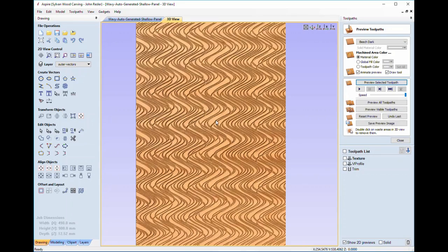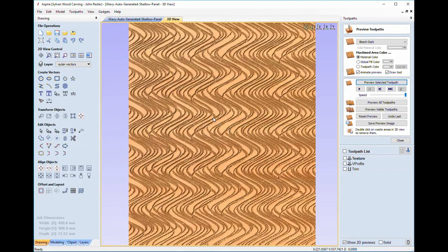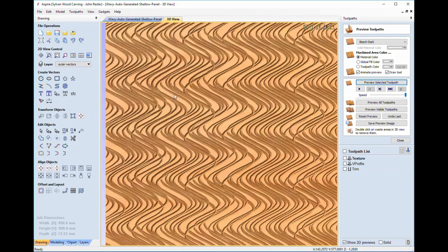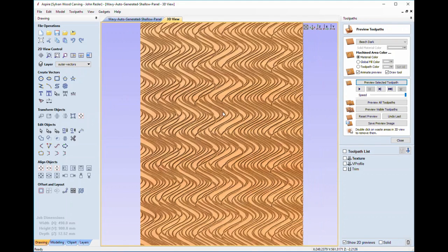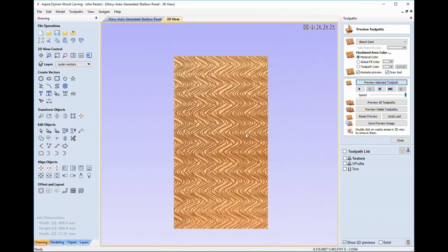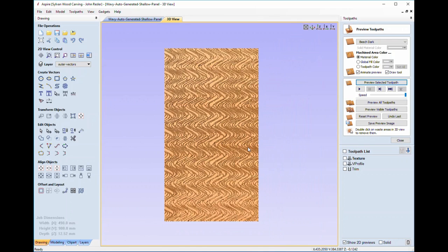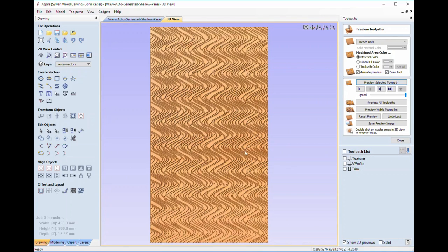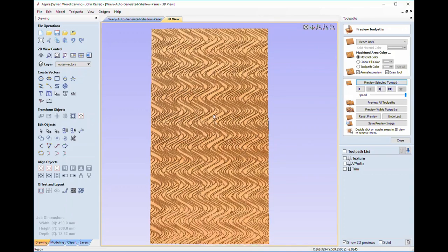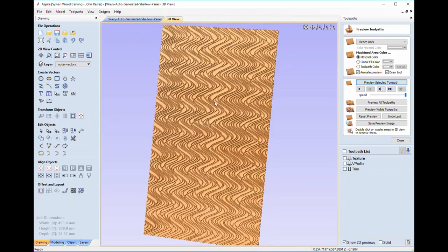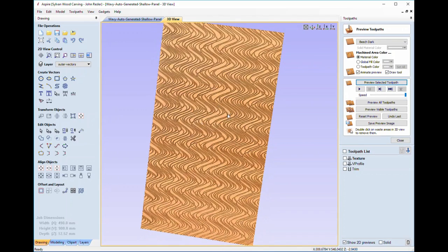Now what you might notice with this one is that because I have the noise and the overlap set to a fairly high value, I'm getting lines crossing back and forth. Okay. Now I have to tell you to be very careful if you decide you're going to do this with MDF, because my first setting was 1/4 of an inch, which works out to be a little over 6 millimeters. Because of that, the MDF was just gouged. It had nothing to do with the router bit or the speed or anything. It's just that I was cutting too much out and it wasn't going to look good, so I stopped it pretty quickly. Okay, so keep an eye on this. Let's remember this, and we'll go from there to looking at the picture of the finished product.